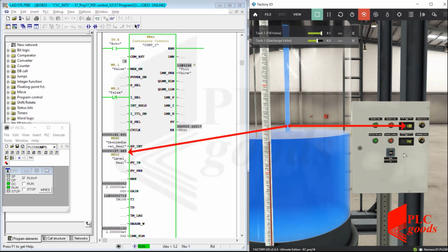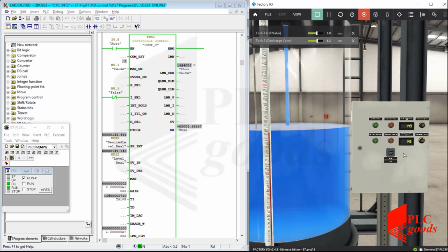If you pay attention to the changes in the water level or the sign of the error values, you will notice that before the water level is fixed at the desired level, it goes up and down around the desired level, and then it stabilizes at the desired level. As I explained earlier, the reason for these fluctuations is the use of the integral term of the PI controller. Again, let's change the desired water level.